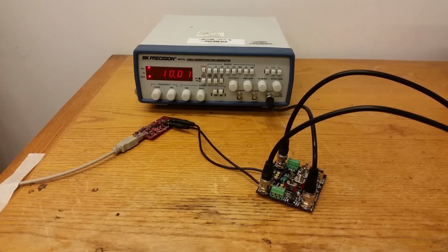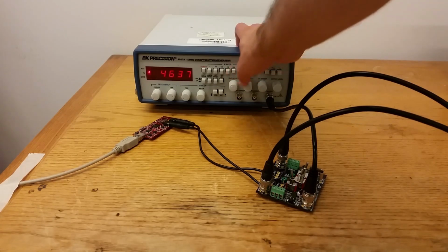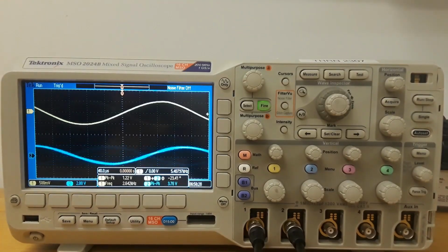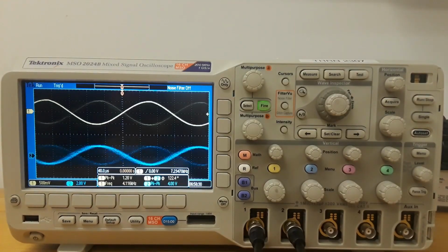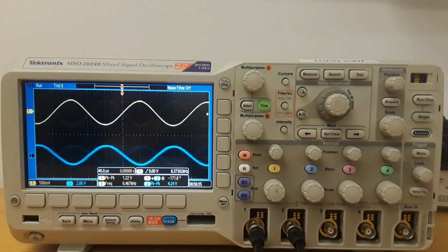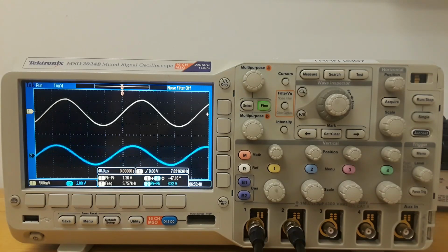So now that we've seen it at 10K, we're going to show what this looks like at 5 kilohertz as well. For this one, we're going to need to change the range on our signal generator. And now it's jumped all the way down to 1,000, because we've changed from 100K range to the 10K range. Let's change the frequency up to something more like 5,000. And again, as I'm turning this knob here, we'll look at what's going on the oscilloscope to compare that as well. We'll make sure we get it around the 5K mark and then adjust the fine adjustment to bring it closer.